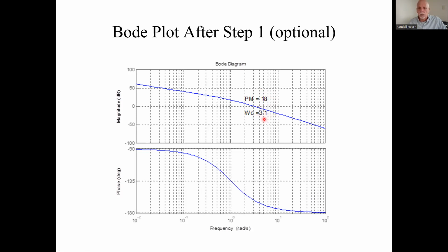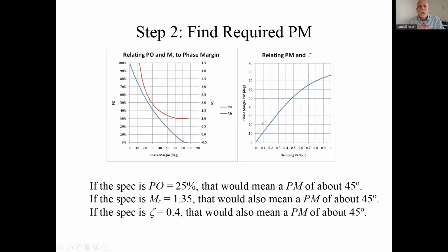And our crossover frequency exactly. So that's step 1. After that, we're going to use the phase margin spec. Now we'll find out where to place the pole and the 0 now that we've got the K sub naught. And I'll save that for a second video.